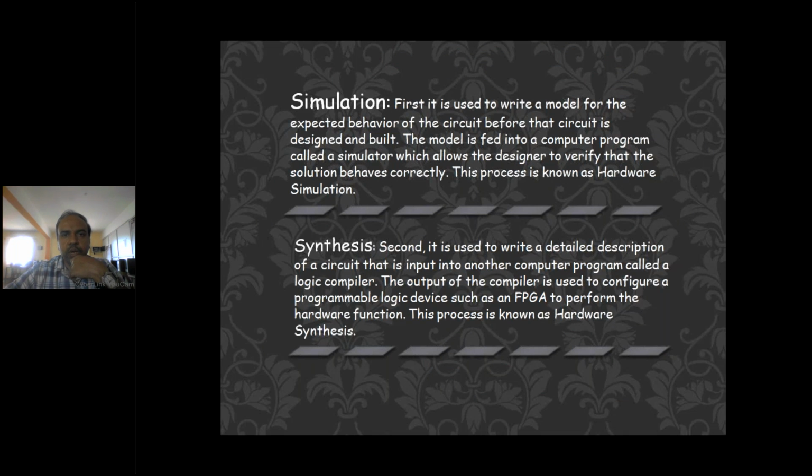First, it is used to write a model for the expected behavior of the circuit before that circuit is designed and built. The model is fed into a computer program called a simulator, which allows the designer to verify that the solution behaves correctly. This process is known as hardware simulation. Once it is working fine, the next part is synthesis.